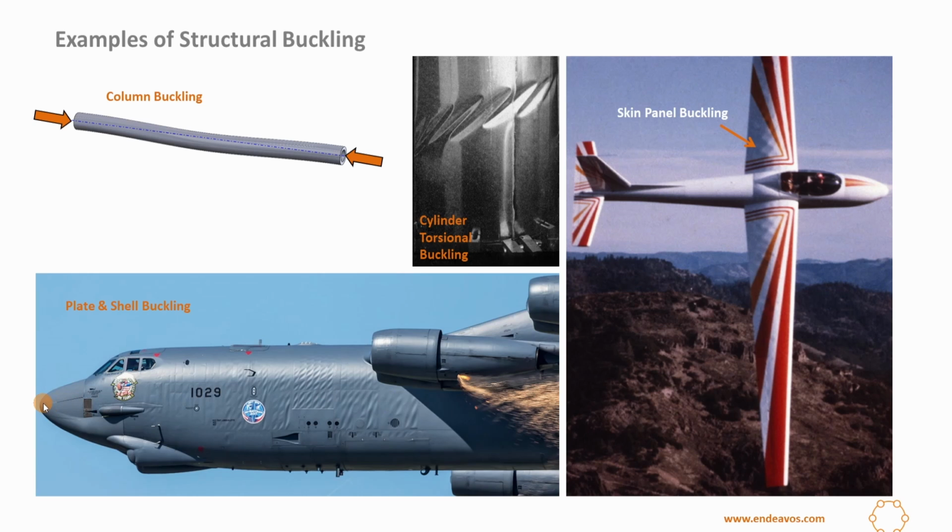So what's important is how much the fuselage, hanging like a cantilever beam, is dropping down at the nose. So I will be tracking this displacement here rather than the lateral buckling or movement of these skin panels here. I hope this clarifies this point.